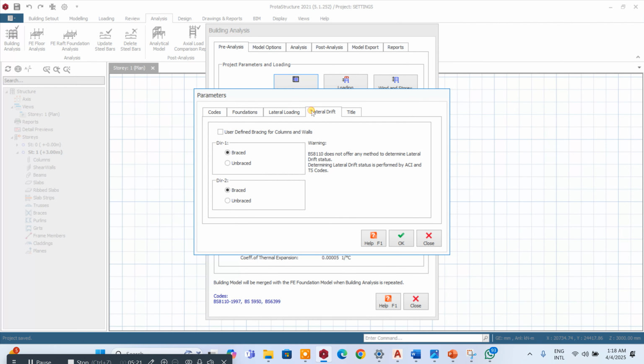So your natural loading. If you have columns that are standing independently, we have two types of columns: braced and unbraced columns. Your braced columns are mostly columns within walls, in a building between walls or having other supports enclosed. Unbraced columns are columns that are standing on their own. So if you are designing isolated columns just standing without walls at the surrounding, you can choose unbraced column for no direction.